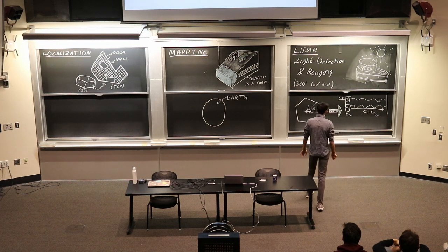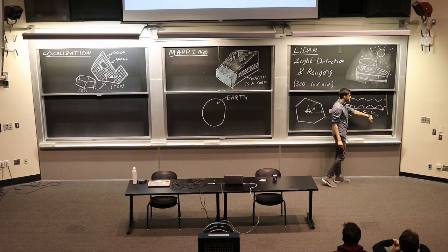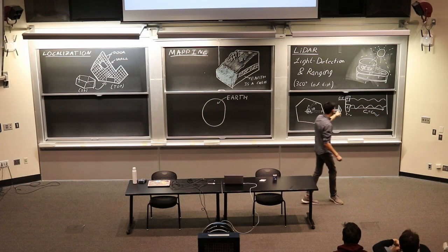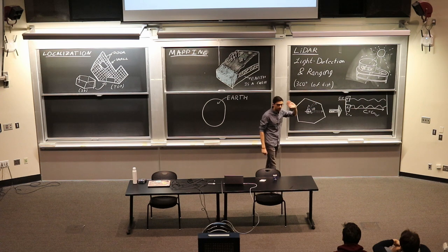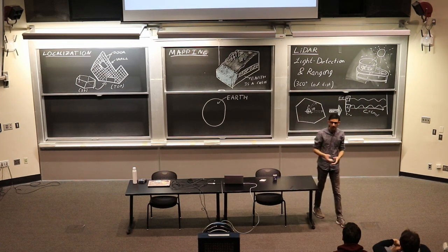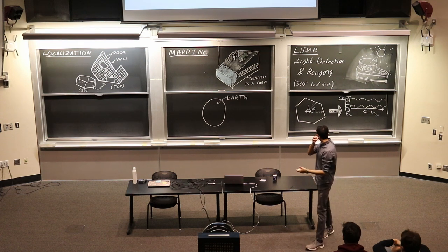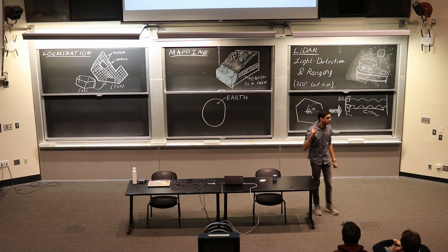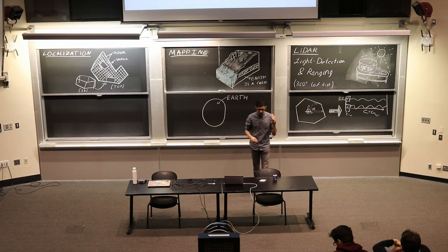And based on that, since you know the speed of the light, or the wave, or whatever you've transmitted, you can then figure out the distance you are from a wall. And that's what a time of flight distance sensor is. We have a bunch. A lot of them use infrared. You'll see the ones in the lab upstairs are infrared. Ultrasound sensors work exactly the same way.